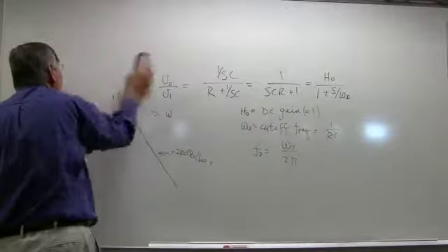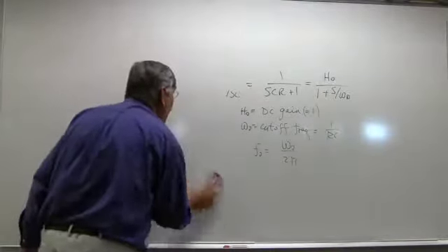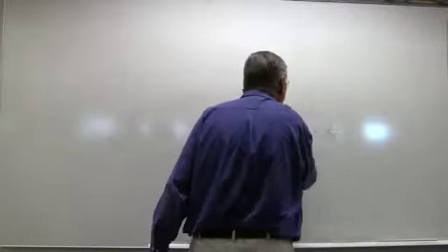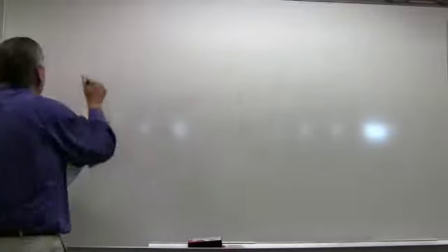In filter theory, one of the things is if you build a filter and you swap the locations of the capacitor and the resistor, you can turn what's a low-pass filter into a high-pass filter.